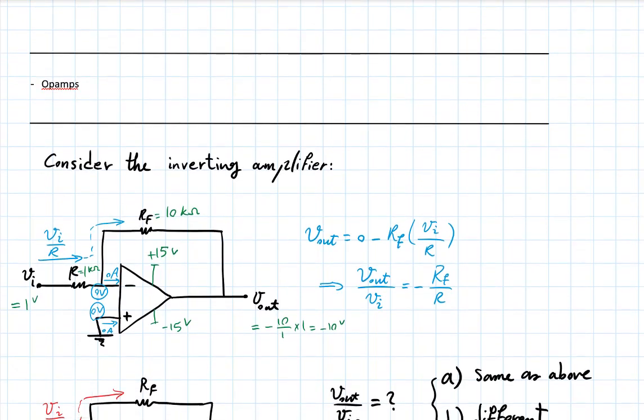What will that do for the voltage right here at the negative input? What consequence will it have for this if that V out goes down further? Look at these two resistors. Between Vi and V out, essentially you have a voltage division to get the voltage of the highlighted node.